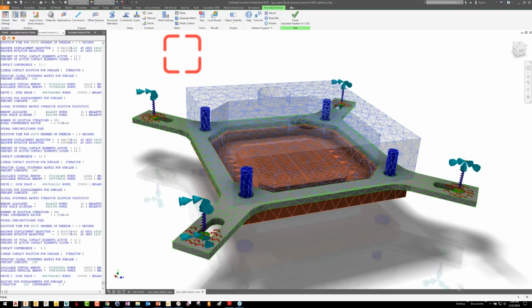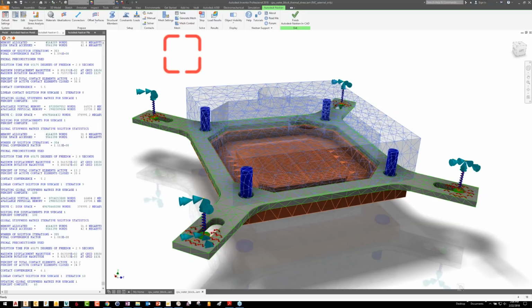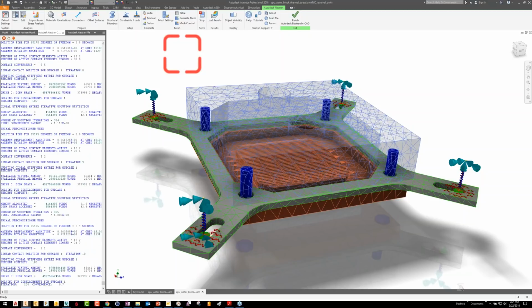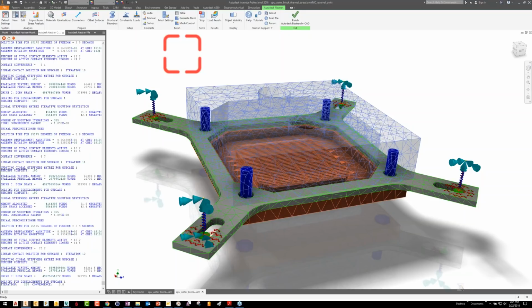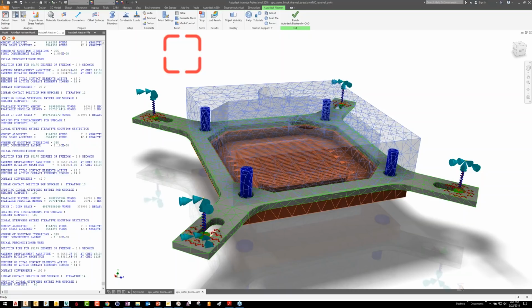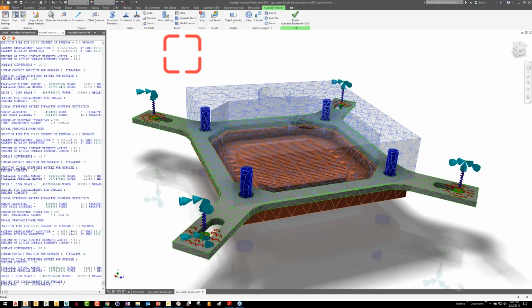We'll see the springs deflecting, hopefully, if I set it up right. But ultimately, the same force is going to be pushed up against those plates. It's just another way to set it up. A little bit more realistic in that I can see how much my springs might deflect. And I could play around with the stiffness of those springs if I needed to.